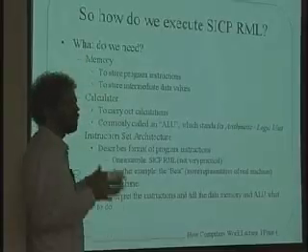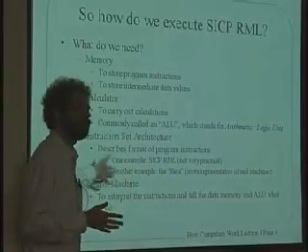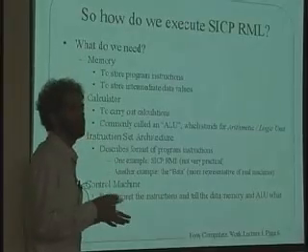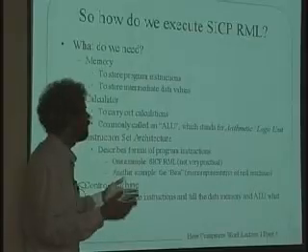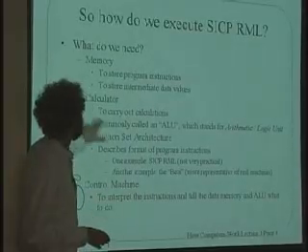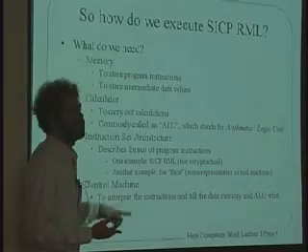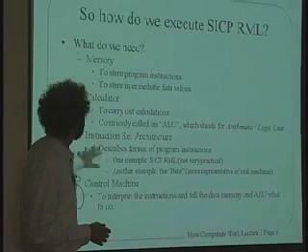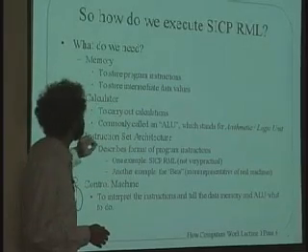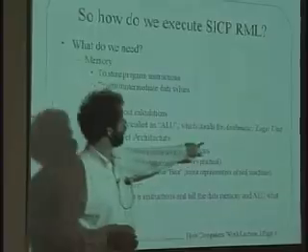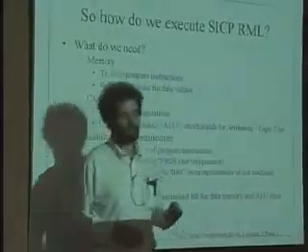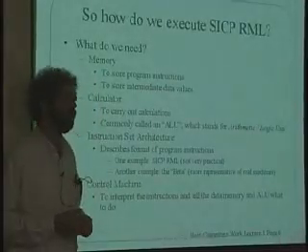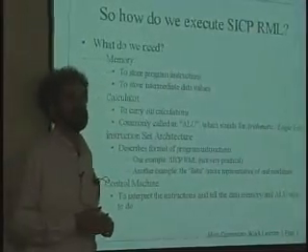The other thing that we would need to use to build a computer to execute that register machine language we just saw is some kind of a calculating device like a calculator in the old days with buttons, right? No one buys these anymore, but something that can add and subtract, do AND, OR, XOR, stuff like that. And what this calculating device is called typically is an ALU, and that stands for an arithmetic/logic unit, because it can do both arithmetic operations like plus and minus and times, and logical operations like and, or, stuff like that.